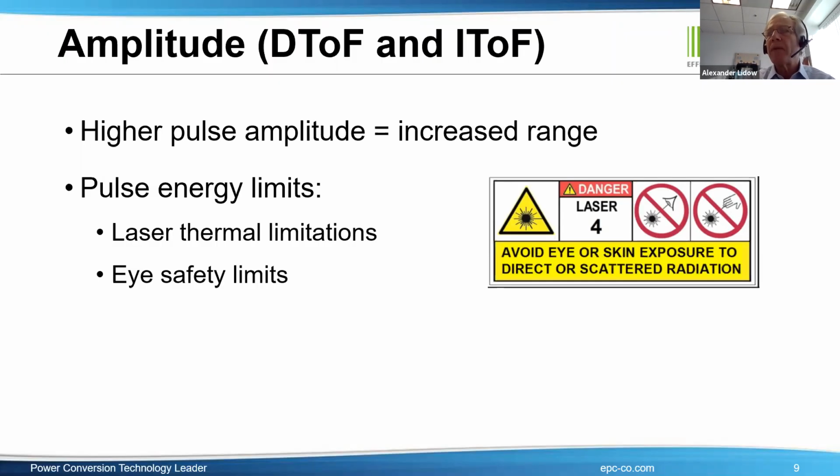But there are limits, and these pulse energy limits come from two things. One is you run the laser with a very high current pulse repetitively, and it's going to hit its thermal limit. And secondly, and probably even more important, there's an eye safety limit. If you're firing these lasers, just think about a whole freeway full of cars firing these lasers everywhere. There are eye safety limits. You don't want to be blinding people with your lidar systems.